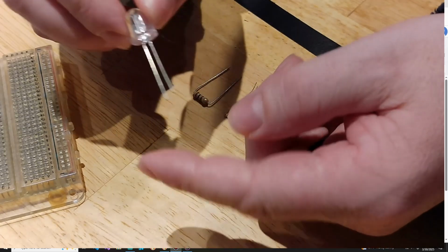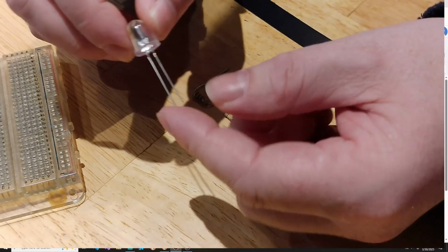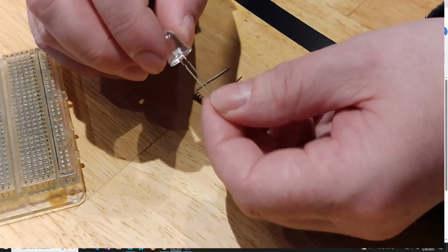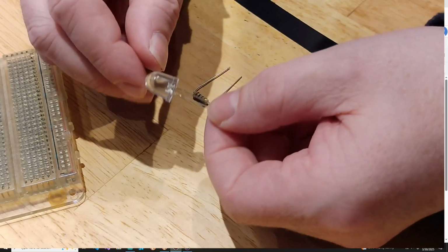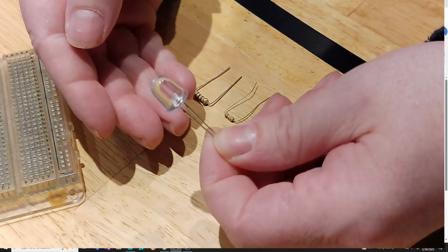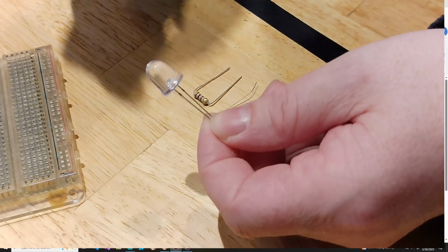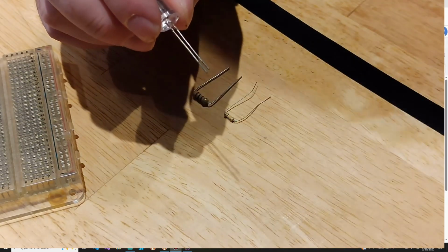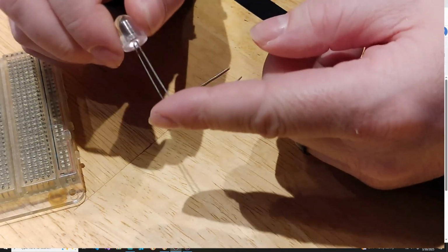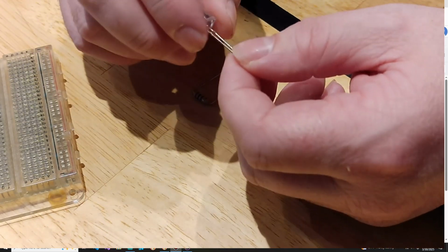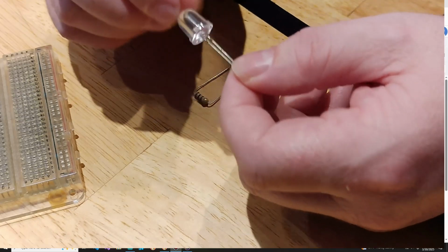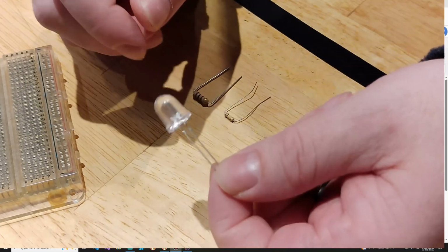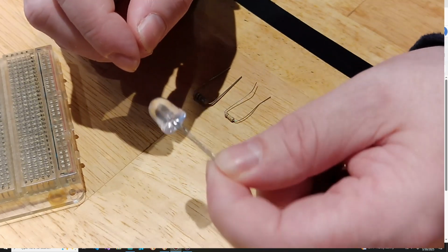They will come in other through-hole mounted styles, like they look a lot like this. This one's clear. Some of them do come frosted to help disperse the light a little more. They do come in 5mm, which is a very popular size, and they also come in a 3mm package. Everything else will come in the range of probably surface mounted, which a lot of professional level electronics will usually deal with. If you're pretty handy, consumer level or personal projects, you can get them on there too. I've done it. And maybe we'll save that for a different class, for a different mini-series. But for right now, we're just going to focus on through-hole mounted LEDs, just like this one.